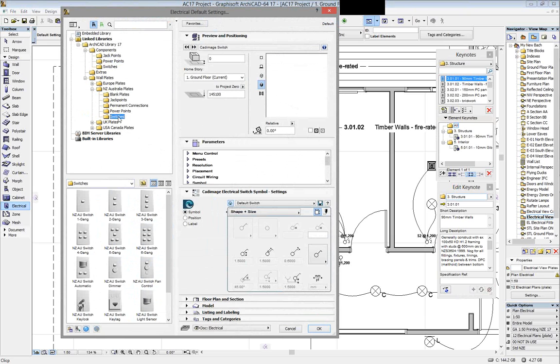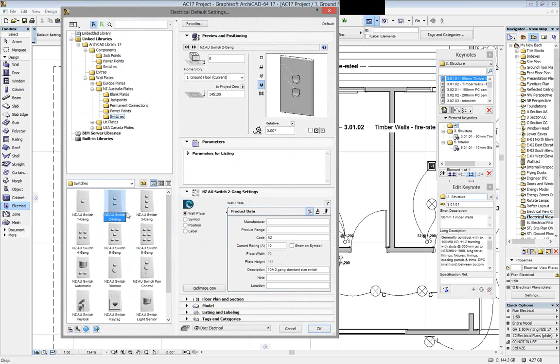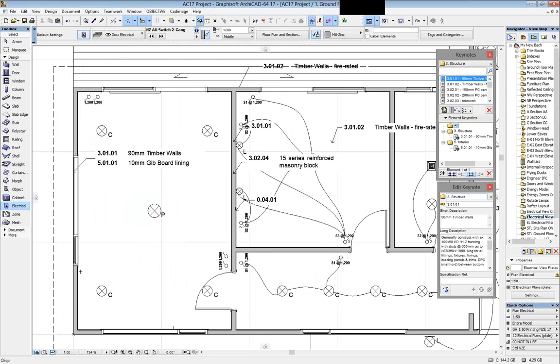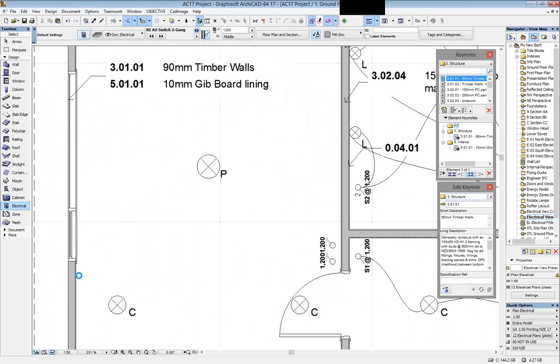And switches. This is built quite like the HPM standard range, so it is quite like what you're going to install. You can set the materials, but their appearance is how they are. The idea is you can actually see them in 3D. So if I click OK, and I place it near this wall, it places on the wall, it's brought out, and it's given me the electrical symbol, because just a simple box here isn't sufficient enough. You can choose if you want to see it or not. I have it currently turned off.